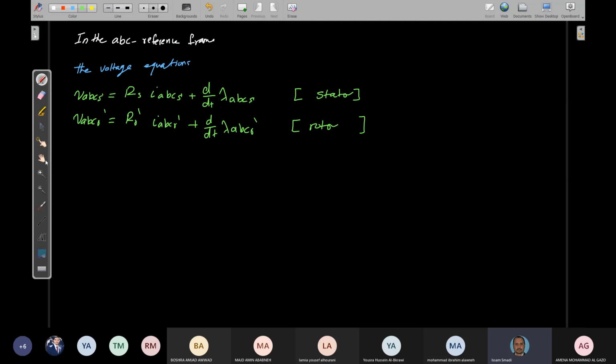Then after that, I think we evaluated the electromechanical torque. So here we can write the electromechanical torque, or the machine torque, simply T_E, which was a function of i comma theta_r.